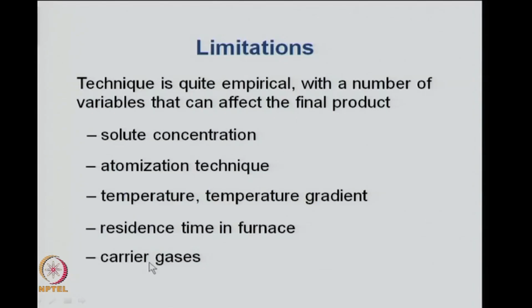Then what kind of carrier gases you are using, because when you are doing this kind of spray pyrolysis, you also add a carrier gas which is a non-reactive gas, and you can vary that carrier gas. You can vary it from argon to pure nitrogen to helium.